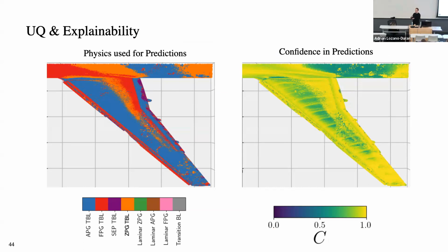So what will happen is that you have the leading edge, then the flow will accelerate very fast. That has to be red. That makes sense, so it's a favorable pressure gradient. Then you will have an adverse pressure gradient. The flow will decelerate, and that's what you get in the blue region. And then the colors are not the best, but you can also have separation. This is the purple at the very end of the trailing edge, telling us that the flow is separating there.